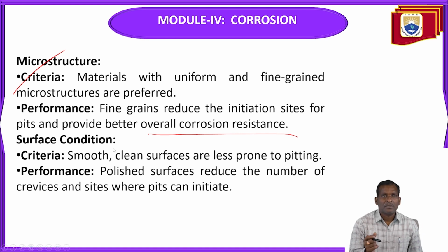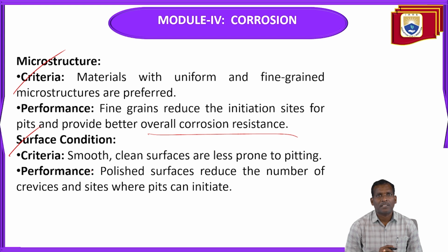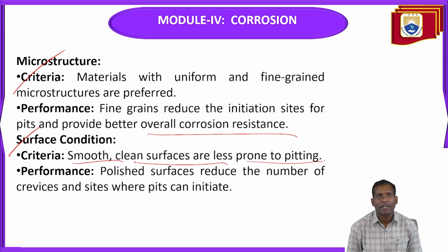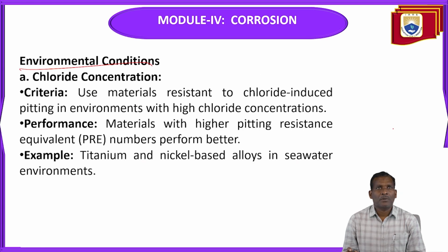Next one is surface condition. The important criterion here is that smooth, clean surfaces are less prone to pitting. In performance, a polished surface reduces the number of crevices and sites where pits can initiate. Like this, you can minimize pitting corrosion. So we have discussed pitting corrosion.